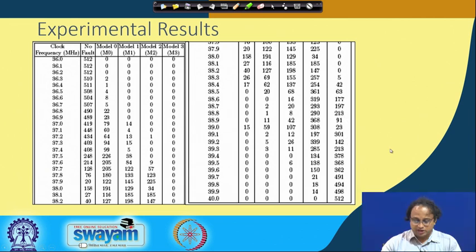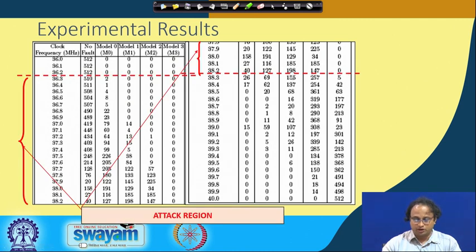So as a result of this discussion, you can actually exploit the faults up to the point where they are not according to model M3. As long as a fault is restricted to model M2, that means 3 diagonals out of 4 are corrupted, albeit with more fault injections, we can still try to reduce the AES key size. In fact, we can do the attack with pretty much one single fault when the fault is restricted to only one diagonal, that is, when I am still operating in a region where the M0 faults are dominating.